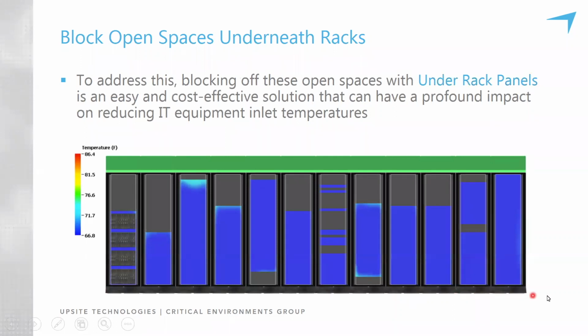And these images are the result of detailed CFD analysis of a computer room. And there's a direct relationship between the evenness of intake temperatures and the efficiency of the room. The goal is always to get intake temperatures into all of the IT equipment, every single U, as even as possible. And that will directly relate to how efficient the room can become.